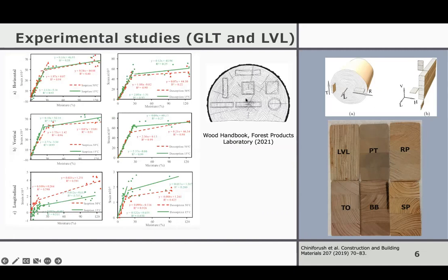So when you look at wood, depending on which section of a tree it's cut from, under moisture changes, for example, if we dry them, they can shrink. And they shrink more in the tangential direction to the grain rather than the radial direction. So that's why this leads to some warpage. So depending where the wood is taken from, under moisture variation, you may have such warpage and twist in wood.